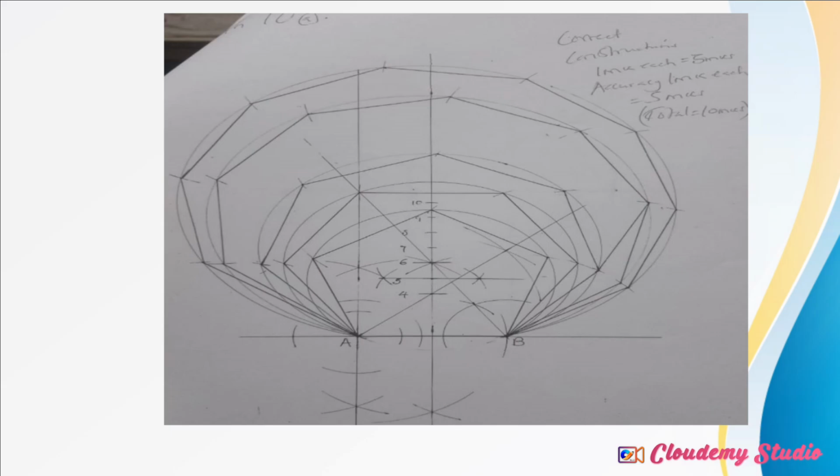Starting at point B, you stretch your compass to any size of your horizontal line. You make a very big arc going towards the right side. Then you also start at that arc with the same radius, make another arc to get the angle of 60 degrees. So you'll find that the 60-degree angle and the 45-degree angle will meet the perpendicular bisector at point 4 for the 45-degree angle, and the 60-degree angle it will be at point 6.